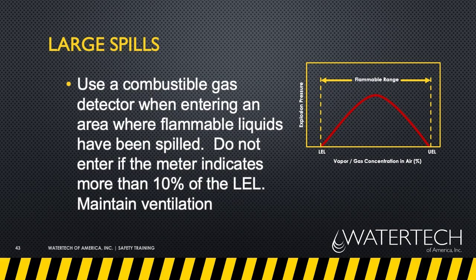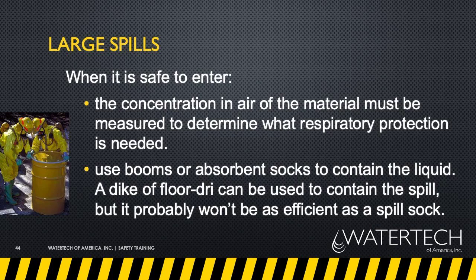Use a combustible gas detector when entering an area where flammable liquids have been spilled. Do not enter if the meter indicates more than 10% of the LEL. Maintain ventilation. If no meter is available, do not enter. It is only safe to enter when the concentration in the air is measured to determine that you don't need respiratory protection. Our drivers are the only ones who are fit tested for respirators. No one else is permitted to go in any area where you're going to need a respirator.